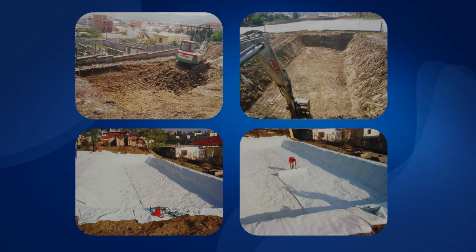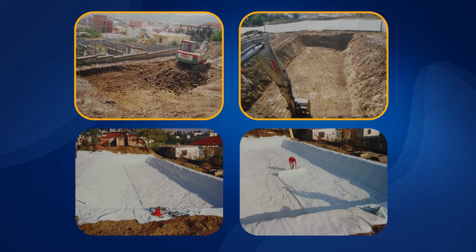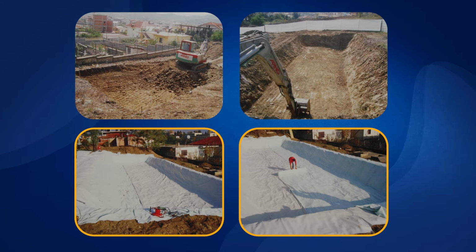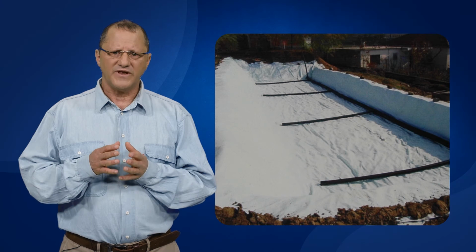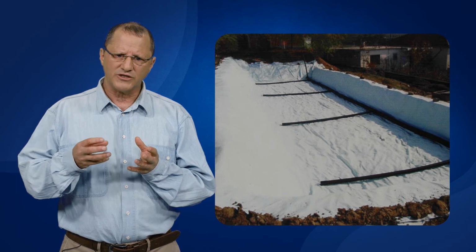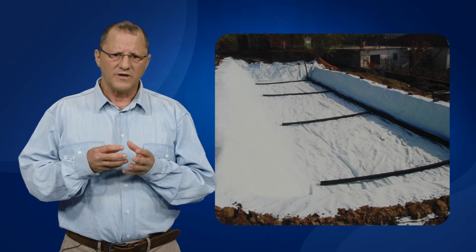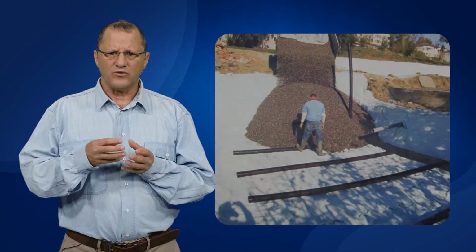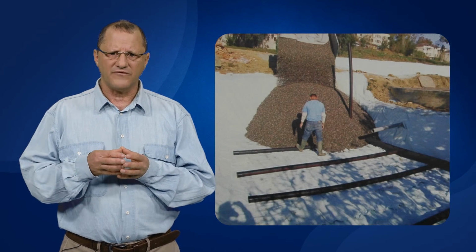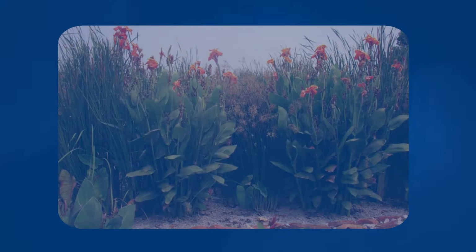Here we can see the major steps involved in establishing a constructed wetland. Initially, the pond with a 1% slope is excavated and lined with polyethylene sheets, ensuring that there is no pollutants leaching into the groundwater. Ventilation pipes that allow aeration of the wetland's bottom are introduced, after which the wetland is covered by the filter bed materials.